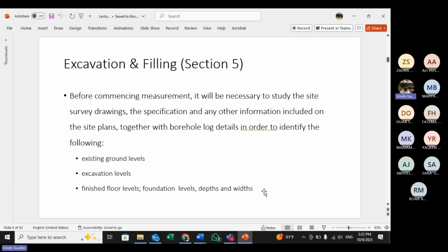It's basically a sample of the soil which you take by digging into it. So it's not the actual excavation. It's a very small hole which is done like with a drill. You have seen the drill machine which you use for drilling in the wall. So it's slightly bigger, and you drill it in the ground, and it will extract the soil sample from it. Okay, it's called a borehole.